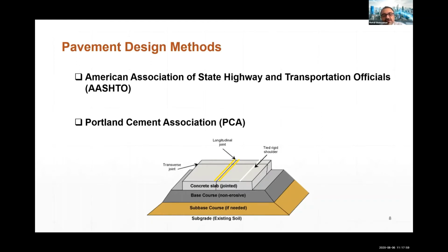So in this research, we employ a numerical method to obtain the critical internal moments and forces, as well as an experimental study for assessing the existing design of the bus pads in Baltimore City. The soil and slab stiffness were taken into account, and more realistic methods to apply the moving and temperature loads were used to analyze the load distresses, soil pressure, and slab strength.